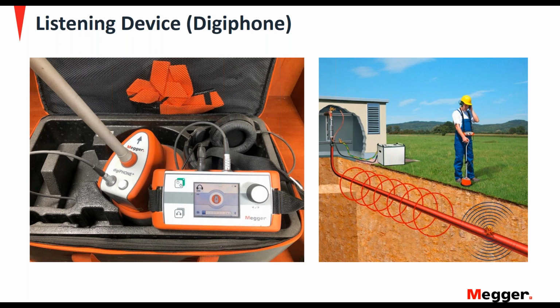Sometimes, even with a lot of joules, we have what we call a quiet fault. When you're standing above it, you can't hear or feel it. Also, sometimes the arc reflection method doesn't give us a distance. In that case, we may have to walk the entire cable path. We know the fault is on the cable somewhere, but we could have a 2,000-foot cable and we don't know where the fault is. In cases like this, the Digiphone is invaluable. It's really our friend. It's going to save us time. It's also going to reduce the number of thumps we have to put into that cable.